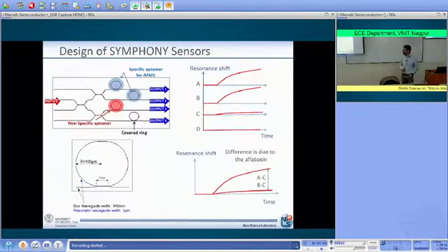And here are a few data about the kind of rings that we are using. In order to get a high quality ring, we use a very large microring resonator, so the radius is 100 micron. And then what we do is place more microring resonators in parallel in order to increase the amount of data that we are collecting.